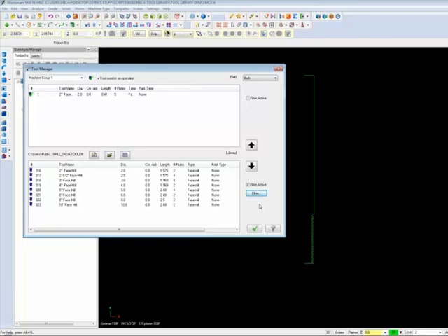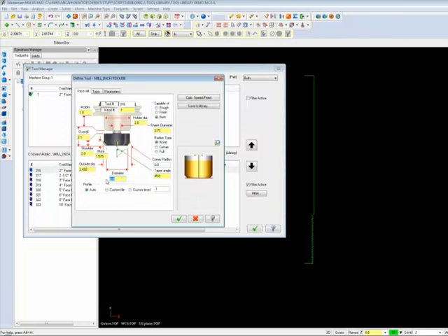Stay there. And it sounds like Jay's got something he wants to add to that. That's why I say, Micah, don't move, because this question is, for example, pick the 2-inch face mill. All right, so that profile shows a 45-degree angle. This question gets asked to me a lot, because people go in there and put 90 degrees in the taper angle trying to get a 90 degree because they have a straight insert. See what happens? Put in 89 degrees. That's the closest you're going to get, for example.